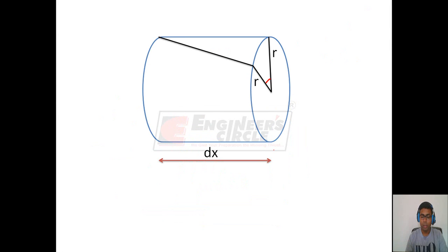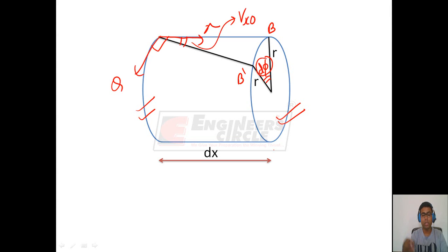The relative angle of twist between these two cross sections is this d phi, that is, this cross section has twisted by an amount d phi with respect to this cross section, and also point B has come to point B dash. Therefore, this change in angle between the x axis and the theta axis, which were initially perpendicular, is gamma x theta.